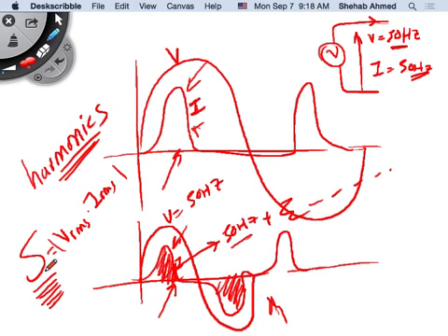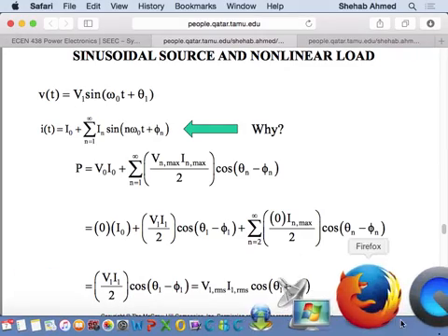So these harmonics are really bad, right? They cause you to buy more expensive equipment because you have to rate it to larger values. They cause losses in the system because currents are flowing. But we have to deal with them because this is what power electronics does to a system. Power electronic circuits are nonlinear loads. They don't respond like a linear load unless you control them to look like that. That's something else. So we'll stop here for now. We'll continue next time.